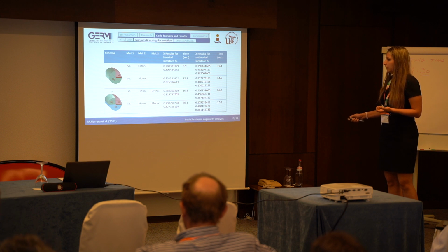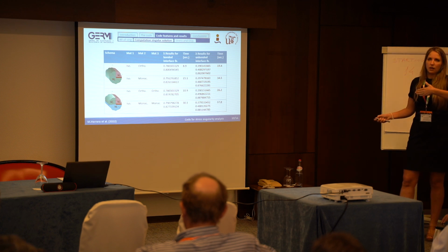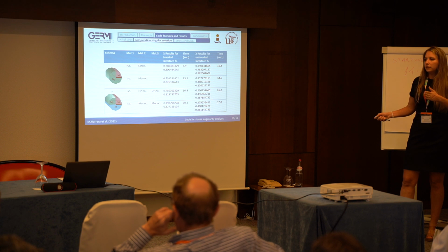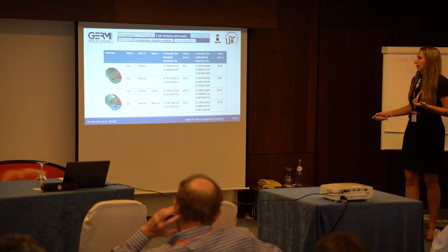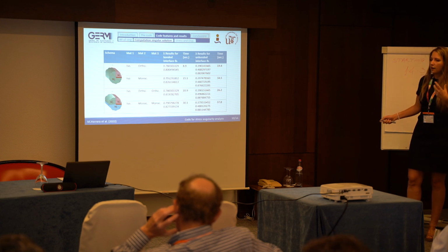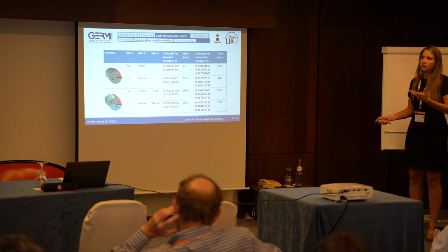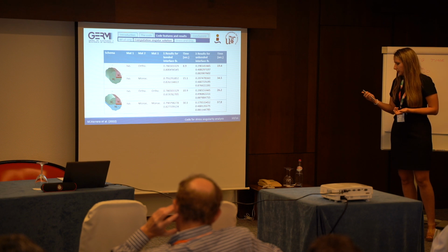Also, the difference between this and this case is the position of the fiber, because when you have an orthotropic material, you can rotate the fiber of the material to have a monoclinic material or an isotropic material. The time consumed by the computer changes, because the transfer matrix is heavier than for an orthotropic or isotropic material.